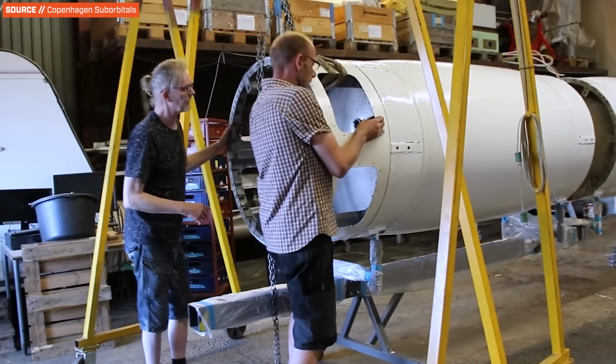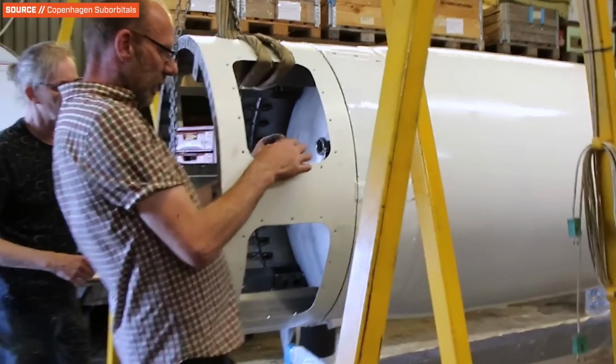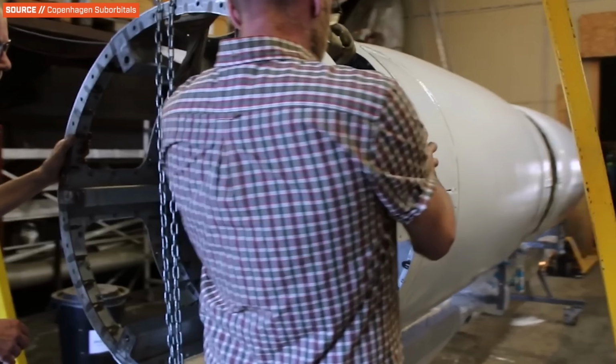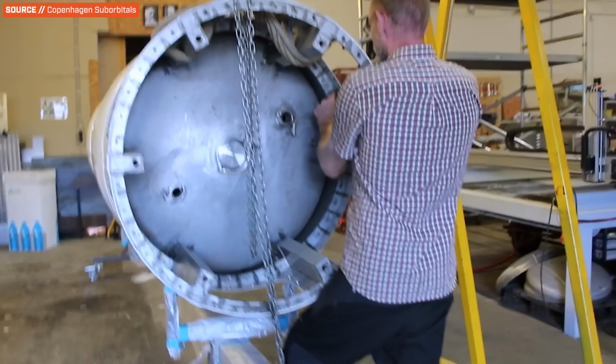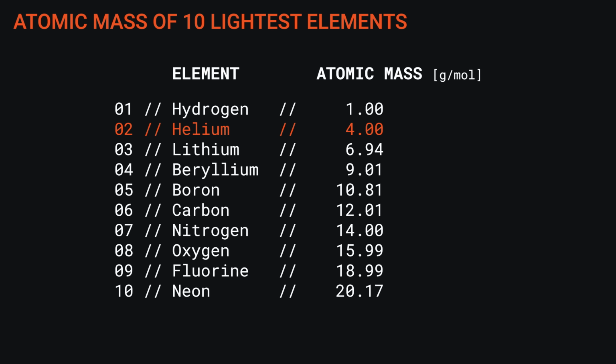And as the name implies, cold gas thrusters often use gaseous propellants, which are less dense than a liquid propellant-filled tank. However, nitrous or butane can be used, which are stored in liquid form under pressure. And of course, a less dense propellant means it requires, again, even bigger and heavier tanks to hold the same relative mass of propellant, which has a bad runaway effect and ultimately takes away from your payload capacity in a hurry. Cold gas thrusters typically use helium or nitrogen for their high compressibility and relatively low molecular weight, which means they can be thrown out at greater velocities. Hydrogen or other propellants could also be used, but I haven't really seen any good examples of those.